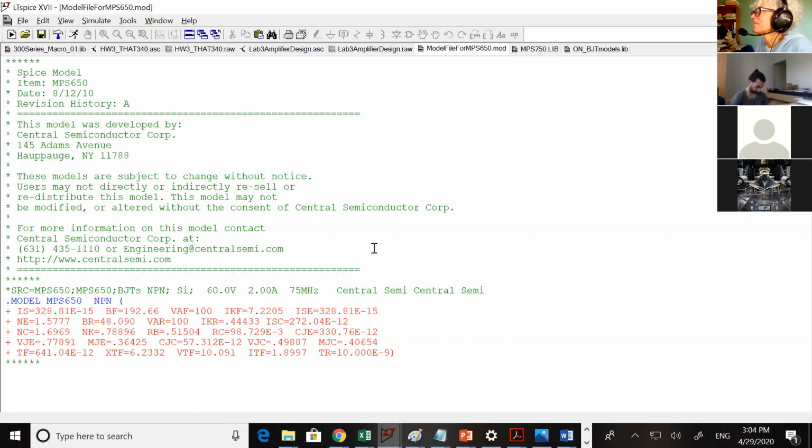VA is already 100. And if you have a current that's less than an amp, that's going to be very much bigger than 100. ro is generally the biggest value in your small signal model. And 1 over gm is usually the smallest resistance. R pi is usually in between the two, but also pretty big.